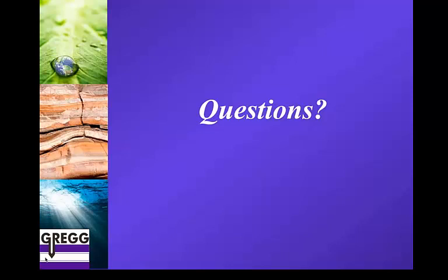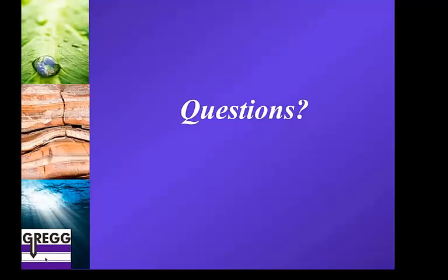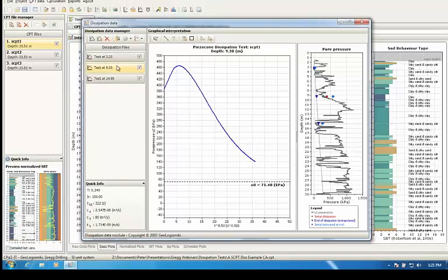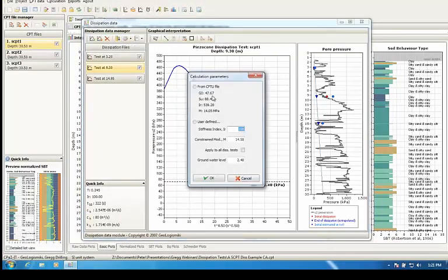Okay, just to finish off, how do you get accurate horizontal permeability in highly dilated soils? Very difficult. Ideally, the best way to get permeability is to do a pumping test or to do a larger scale test. But full-scale pumping tests are expensive, which is why piezo cone tests are often attractive, because if you're going to do CPT anyway, then the dissipation test becomes almost for free, as it were, which is what's so attractive about it.